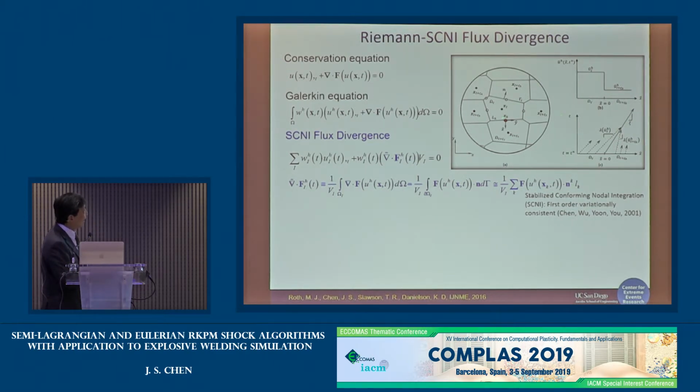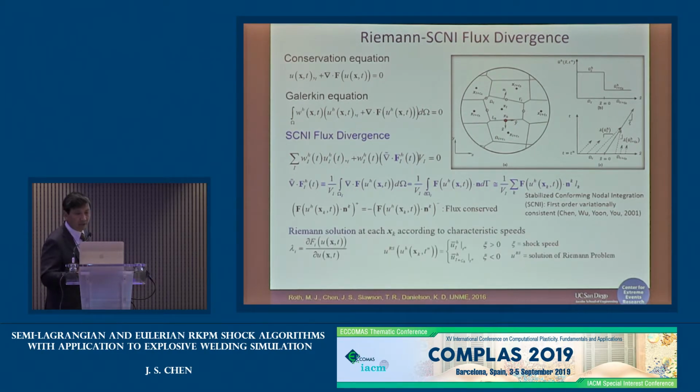The second thing is that I can now introduce the shock physics at the cell boundary, because as I mentioned, shock physics comes from the flux. The jump of flux is the driving force of shocks. And so I don't want to take another derivative of flux, because then again you have to do differentiation, and that depends on your discretization. So we want the shock to be calculated directly from some techniques which will be introduced in a few minutes. This also avoids taking another derivative of f. And here also, if these boundary integration cells are conforming, then the flux is conserved. Very easy to see that.